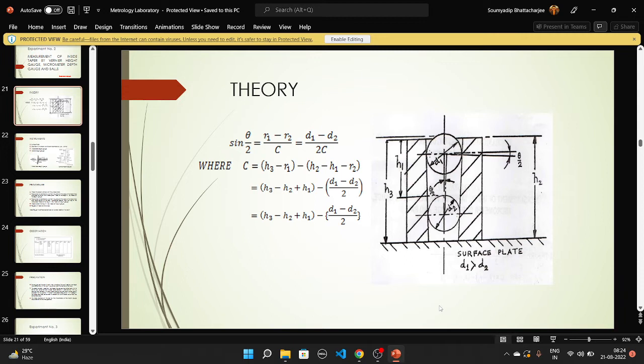But remember that you have to consider the graduation beneath the index line, which is graduated at half the value shown above the index line. Above the index line, the graduation is in the interval of 1 millimeter. Beneath the index line, the graduation is in the interval of 0.5 millimeter. Please remember this. This is an important point you have to consider when you take the H1 value.